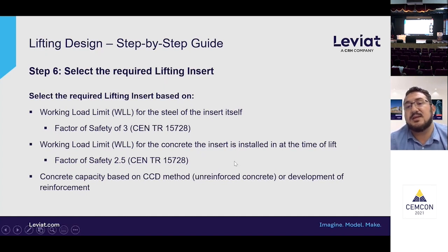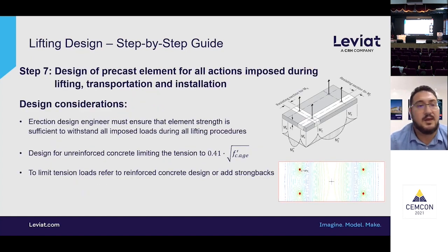When you're doing the concrete designs, depending on the failure modes, there are many that need to be checked per actual lift, but a safety factor of 2.5 is normally used. It's important to note that you have to use the concrete strength at the time of lift, not the 28-day strength, because typically concrete elements are handled 2-3 days after the concrete pour. So you're not getting that full concrete capacity, and that's an important thing to highlight.